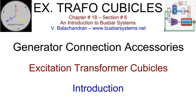The excitation transformer cubicles are connected to the generator terminals through a tap-off connection from the main isolated phase bus. This tap-off connection is the closest to the generator terminal. The enclosure of the excitation transformer cubicle is insulated from the tap-off connection by rubber bellows. An enclosure bonding bar is installed close to the rubber bellows.